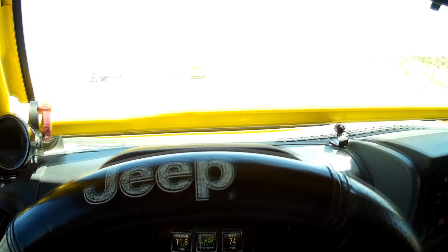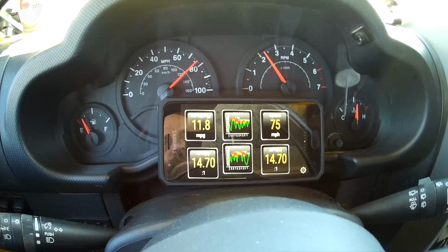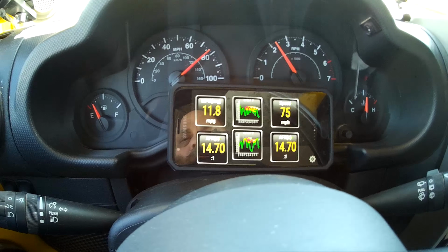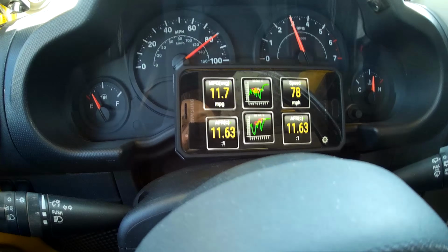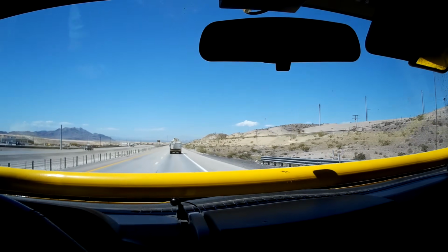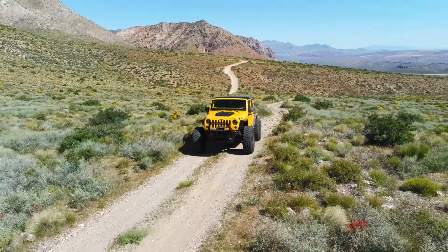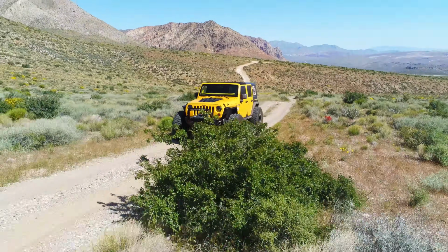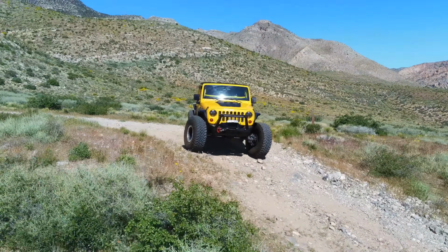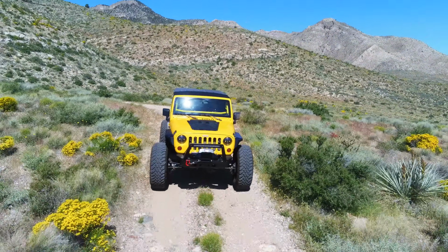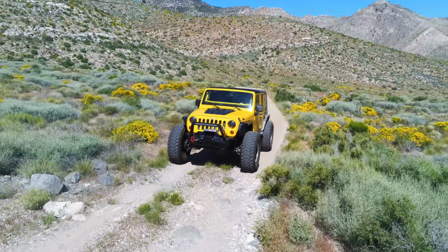Now here's something you can do for economy. You can see that we're in closed loop right now, running off the O2s. If I were to speed up, which I'm doing right now, notice we went open loop. So the moral of the story here is if you want economy, watch what mode you're operating in, closed loop or open loop. It's very easy to pick up economy by driving consciously. So the point I'm trying to make is monitor what mode you're running in. Performance enrichment, deceleration fuel cutoff, open loop, closed loop. This can get you better economy. There's no reason on some of these long stretches, if you just slow down 1 or 2 miles an hour, you can't get better economy.